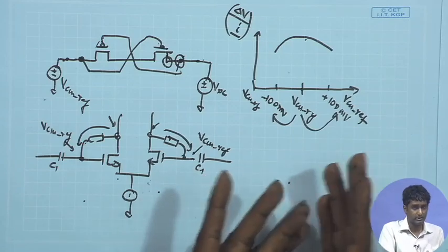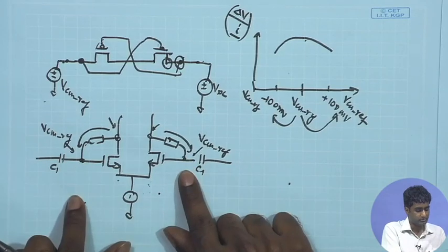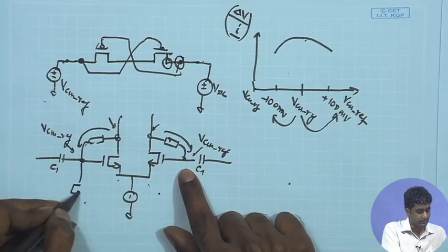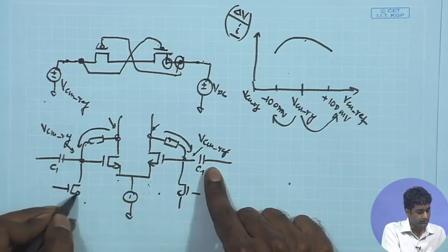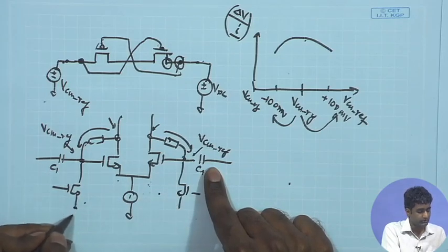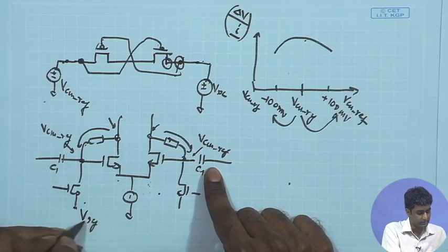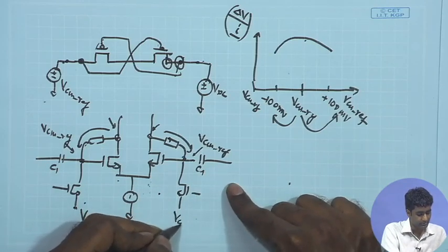So, the other option, if you want to use a DC source, is that you connect some switches over here, and at t equal to 0 you provide some DC potential over here, which is equal to the VCM ref as you suggested, and here also VCM ref.